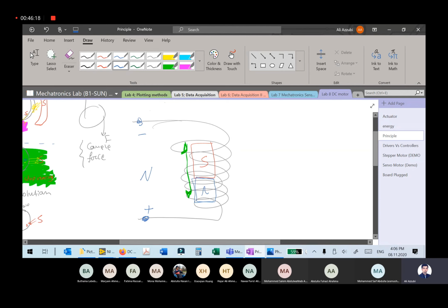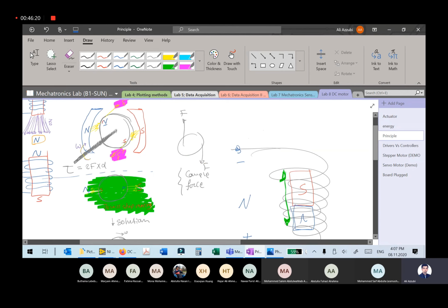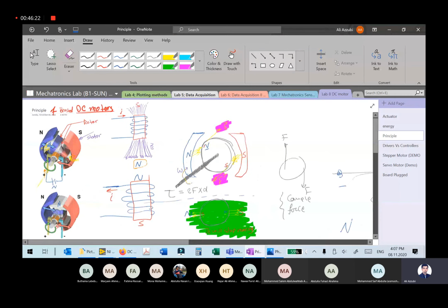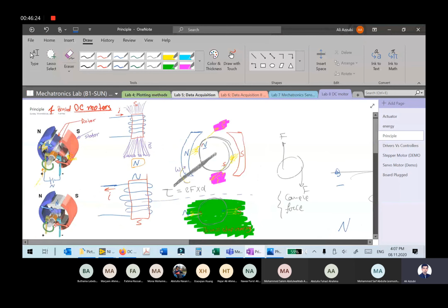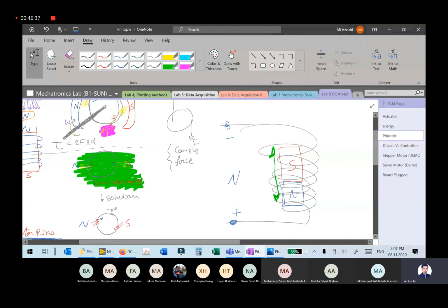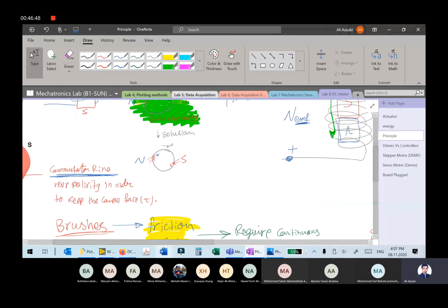This is happening in the brushed motor. You have a moving coil, which is your rotor, and you have two magnets. So basically, if you rotate the motor manually, you will generate some electricity. Circuit-wise, we'll come to this. We call this VEMF, electromotive force. This is due to the motion of the motor. So this is a very nice question.